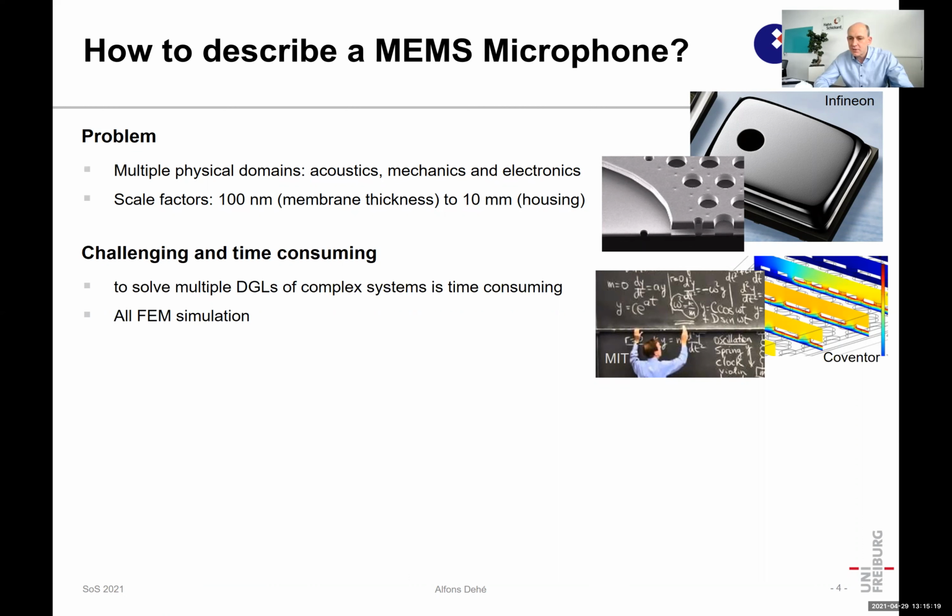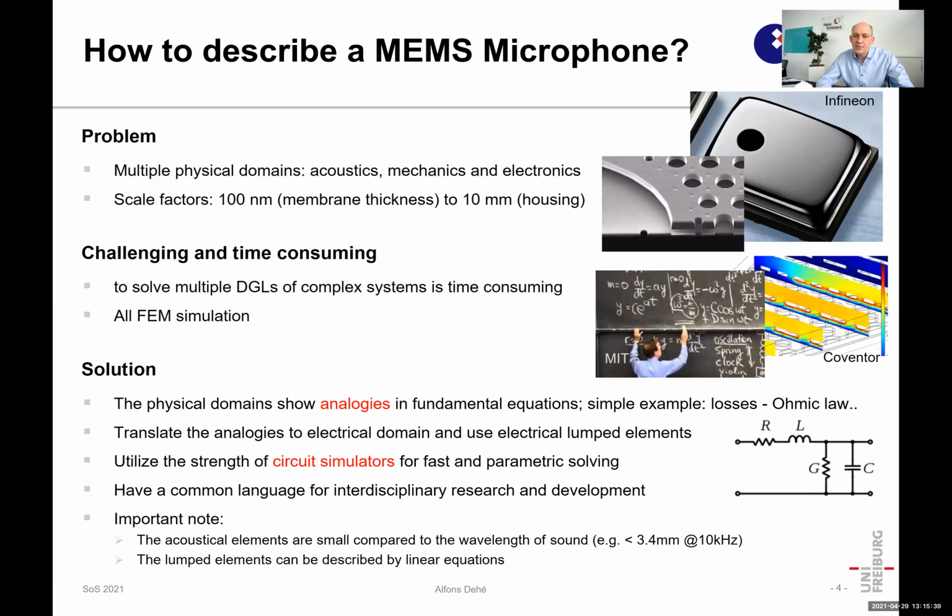Classically, you start with some differential equations to solve the situation of motion and fluidic situation, as we discussed last time with the Euler equation. This helps to get started and is maybe valid as long as the system is not too complex. So what I propose in this lecture is using circuit simulators and do the representation of the individual physical elements in your device with analogies from mechanical to acoustical and electrical laws.